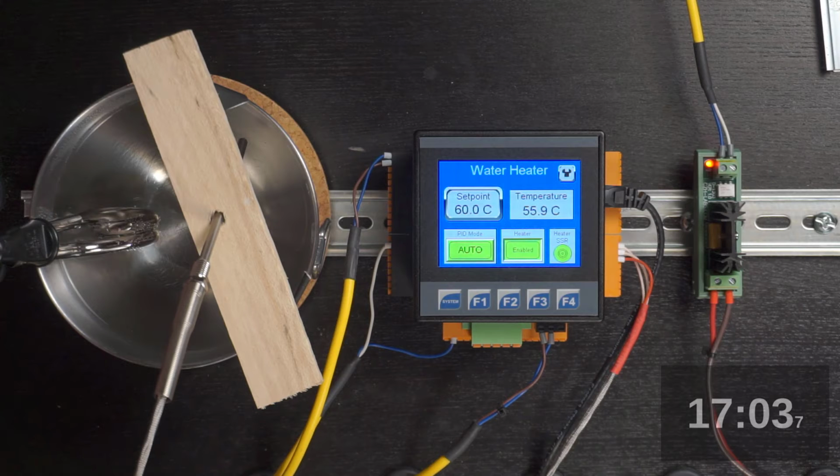Now one thing that I'm keeping my eye on here is that we're actually getting further away from the set point. So that's obviously a concern, and if it continues, then my thought would be that we may have a scenario where the integral term is creating problems. That's not unusual in some applications.